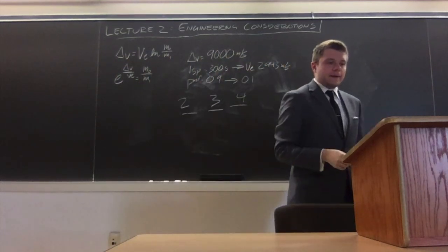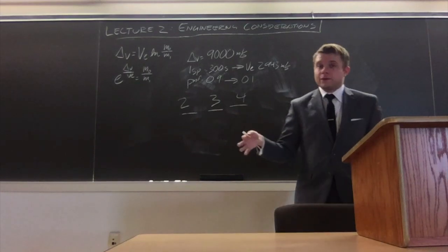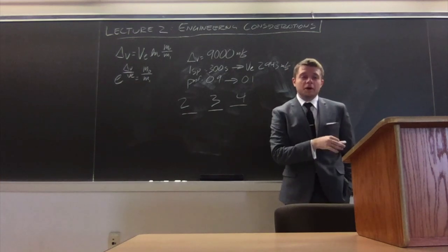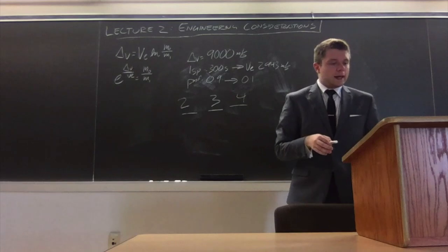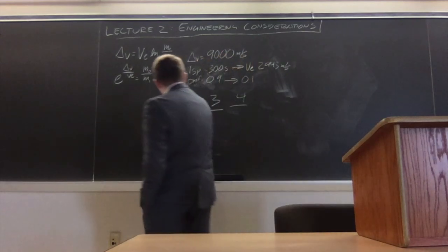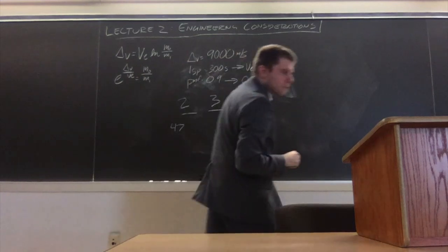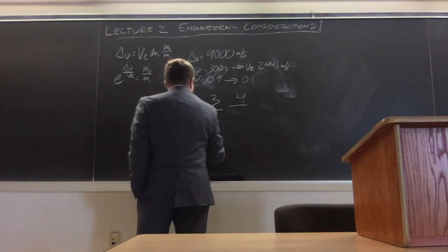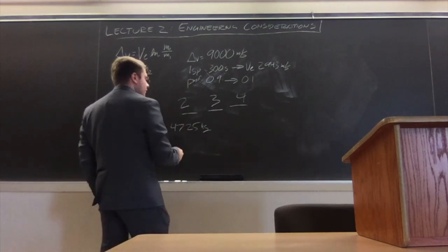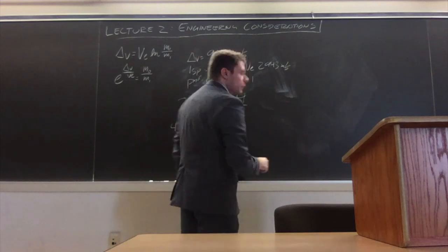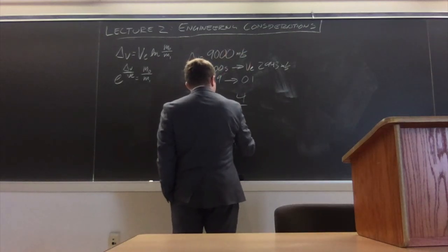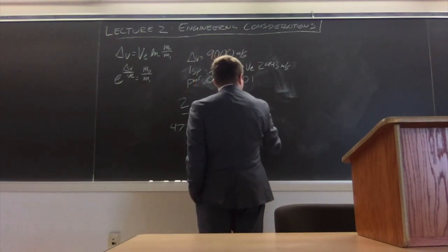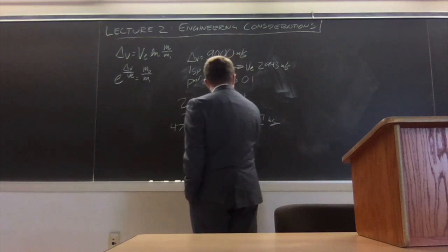So, 2-stage rocket. I started with an input mass of 1 kilogram, and then worked my way progressively through each stage. Is it realistic? No, we'll talk about some of the deeper considerations of this in the next part of this lecture, but basically the total mass of the first rocket was 47.25 kilograms. That's with payload, with everything else accounted for. The 3-stage rocket had a total mass of 41.07. And the 4-stage rocket had a total mass of 36.51 kilograms with these inputs.